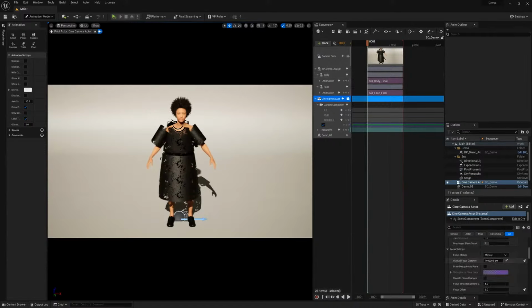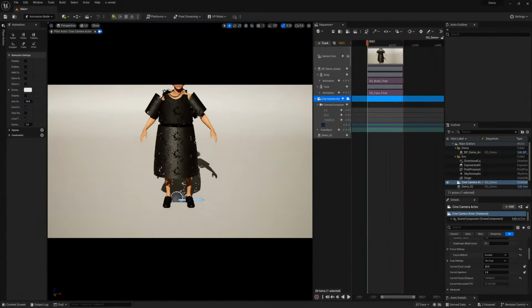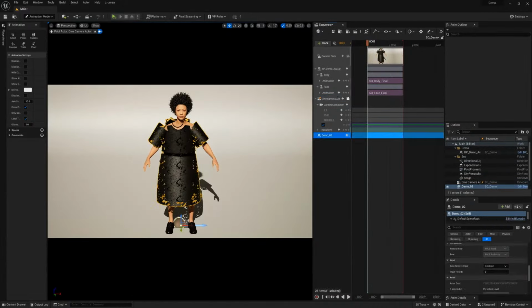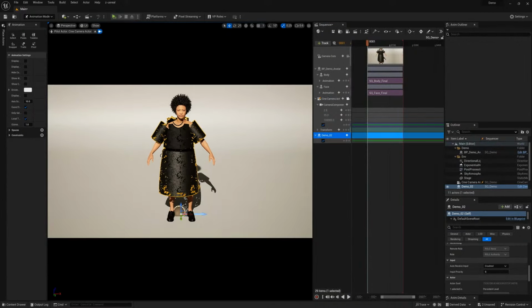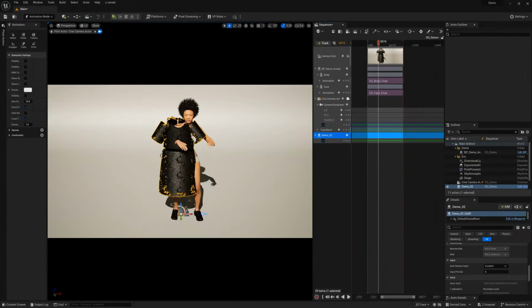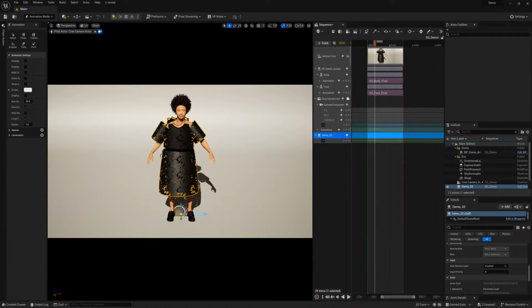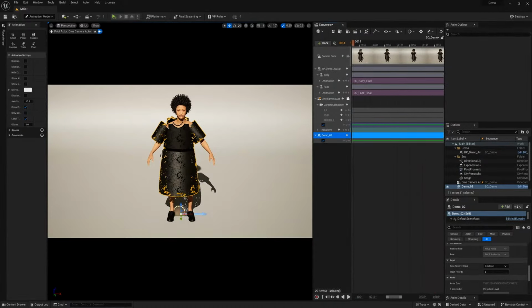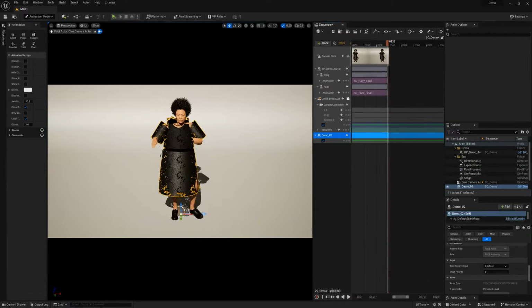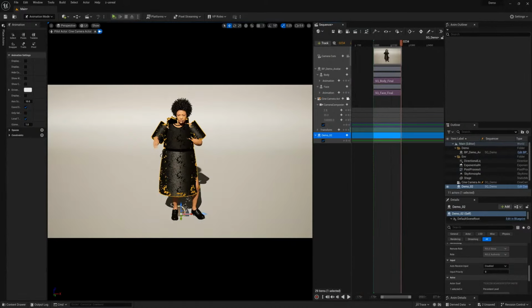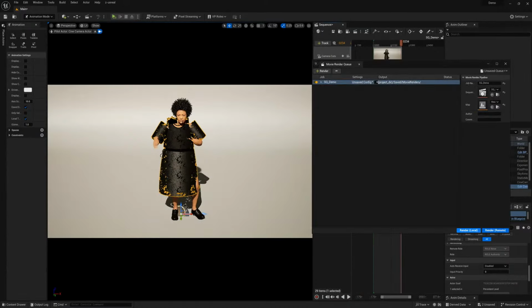So it is disabled. And don't forget to turn on use cache to generate geometry cache for this. And then everything is ready to generate cache. So edit range. Once it's done, just go to render and double check your sequence name and your level here, and then start rendering.